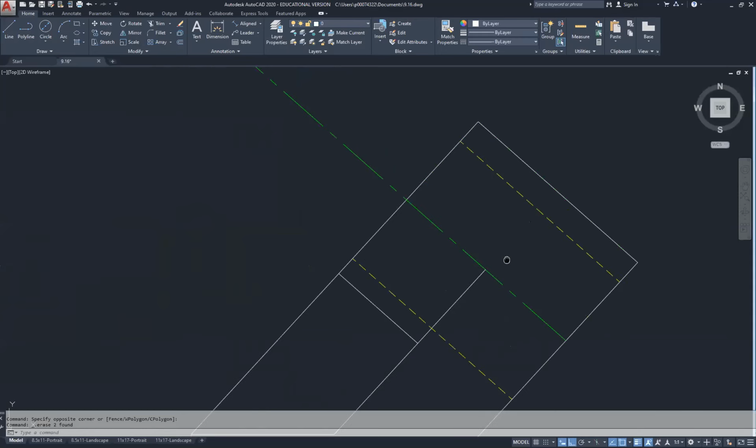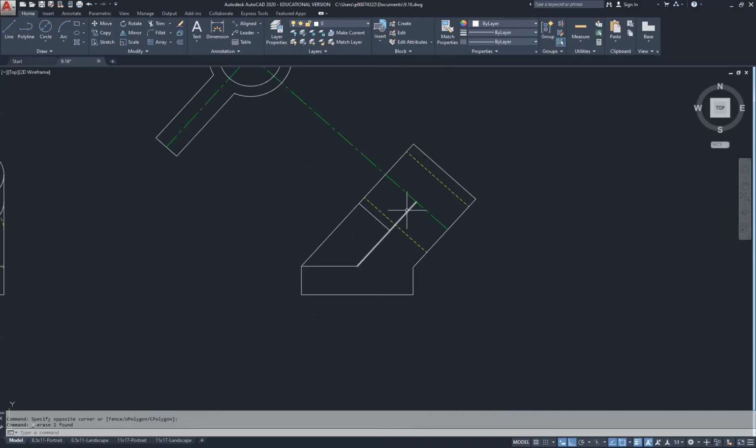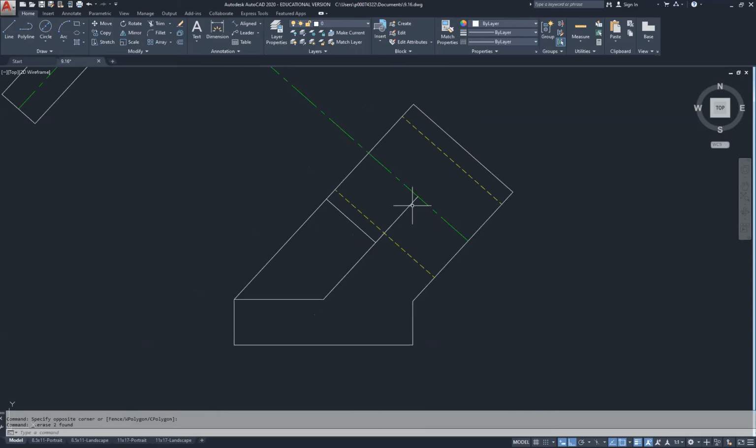Now, there's a detail here. You'll notice this in the book, that this should be curved right here. Even though it's not actually a curve in there, there's no fillet on this edge. What we're going to put in is something called a runout. It lets the person reading the blueprint see that this line stops when it hits the circle and becomes part of that object.